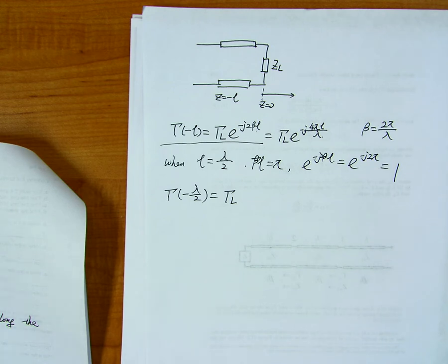So if you can find gamma L equal to 1, then the corresponding gamma L is at this point, which is equal to the radius of this big circle. And if gamma L has a phase, then you can just move that gamma L in this complex plane, where the region of the complex plane is here.